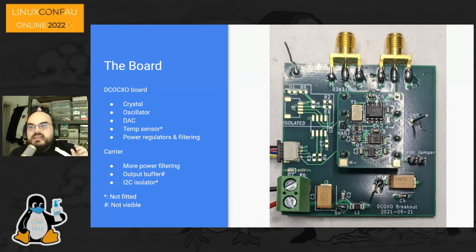And then the silver pad you can just see to the right of the oscillator is meant to be the pads for a TMP117. Unfortunately, they are really small. This is surprisingly hard to solder. And if I actually want to get one soldered, I'm going to have to learn to use solder paste stencils. This was reflowed by hand, but the paste is just an issue.